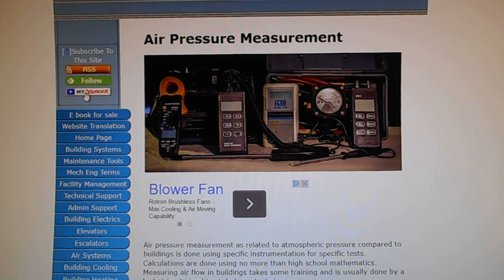To decrease fan speed, a smaller outside diameter motor pulley must be installed. This will result in the motor amperage being decreased. To increase fan speed, a larger outside diameter motor pulley must be installed. This will result in the motor amperage being increased.